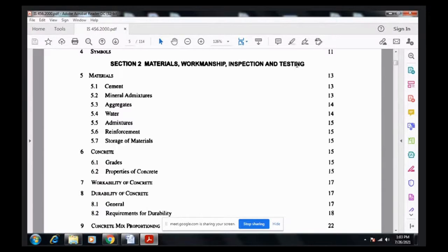We never used to purchase stone chips, sand, or cement from anybody. We used to purchase the hills, and our experts used to blast those stones, and then those stones were crushed in the crusher network on the site itself. We get different sizes of aggregate and stone dust out of that stone, and then, depending on the quality, we use them for different types of construction activity.